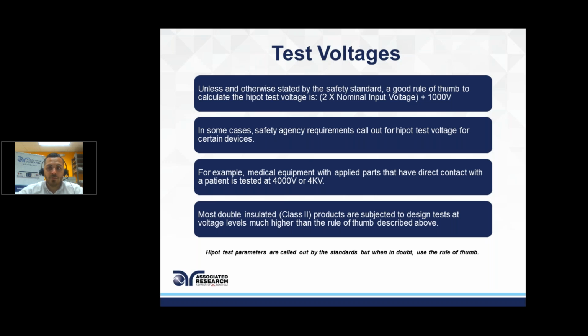But again, if you're ever confused about what you should be testing to, just keep in mind 2 times the rated voltage plus 1,000. If you're at 240, a lot of products now are made between 100 and 240, right? So you'd be at 1480. That would be your test voltage.